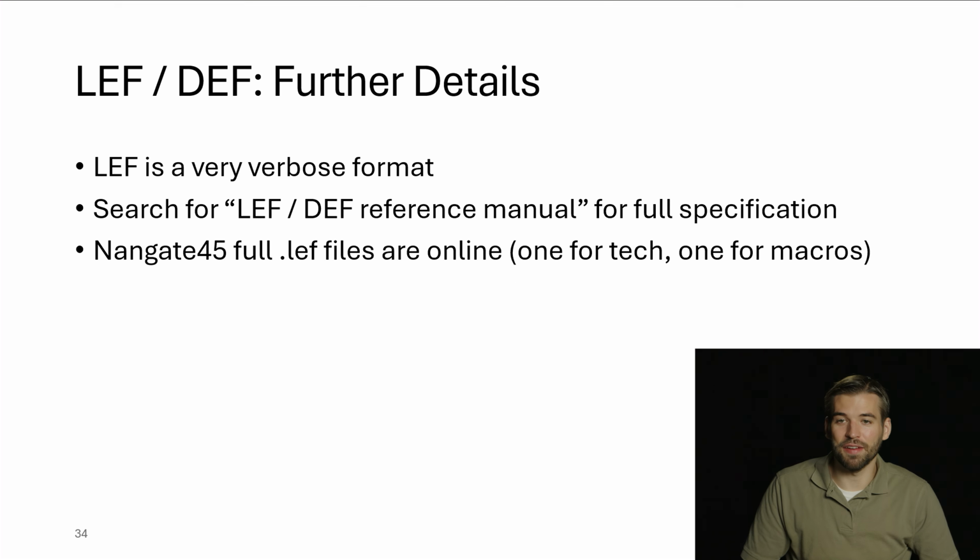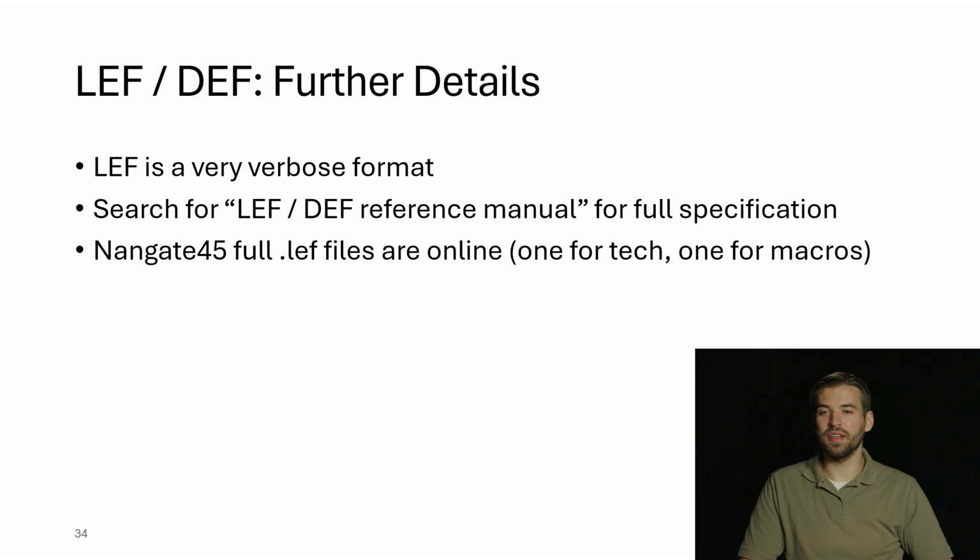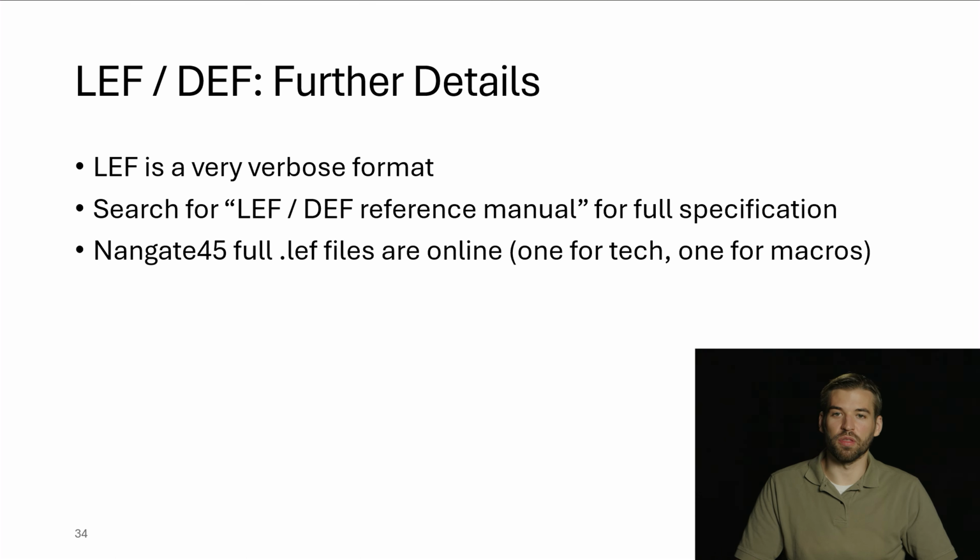So again, LEF is a very verbose format, and you can search for more examples and more definitions in the LEF-DEF reference manual. The NAND 45 full LEF files are also available online. There's one for the technology and then one for the macros or the masters. So you can go ahead and look those up if you want to see more details, including all of the things that were left out.